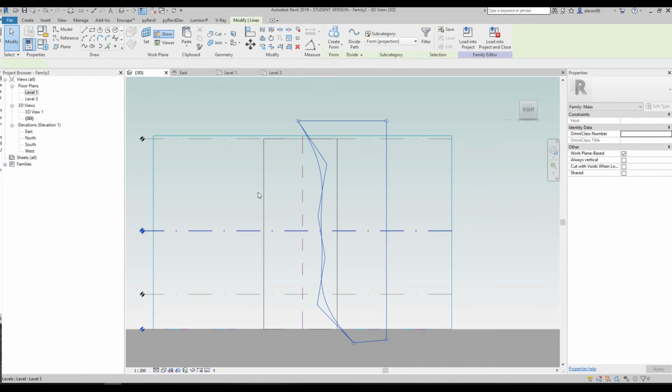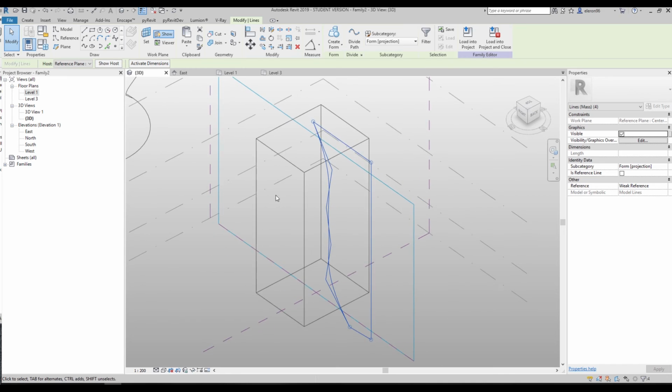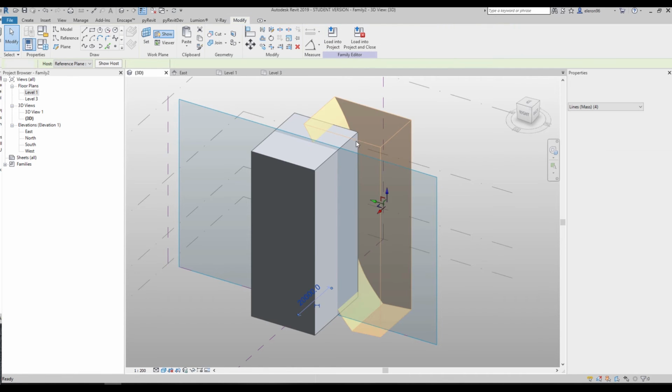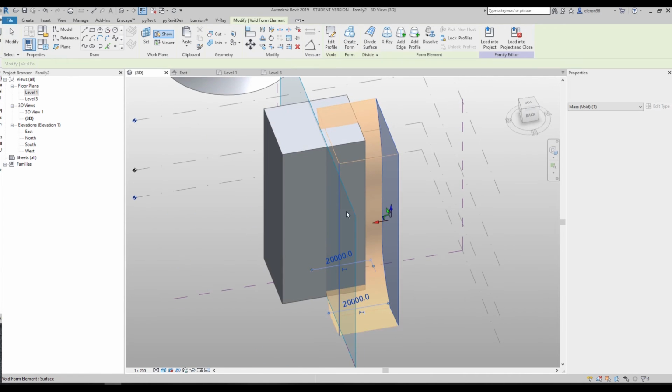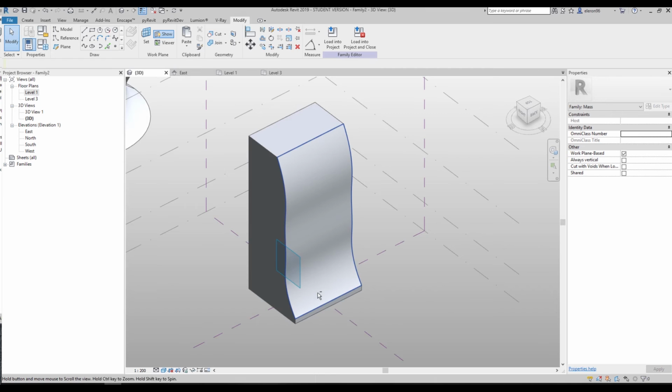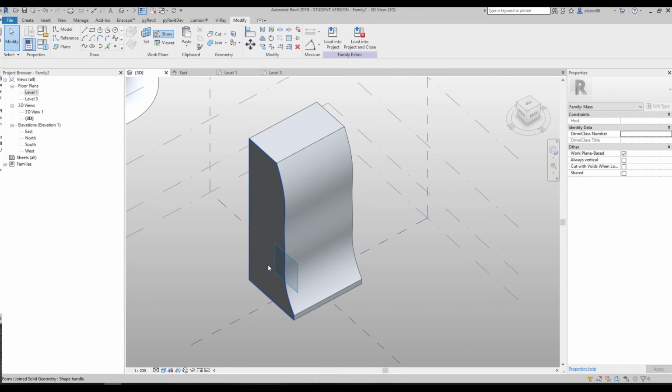Let's select all this shape, I mean all this profile. Let's change the view. I want to change the view graphic because I want to show you everything, and I will use the void form again. Create the void form from this spline. Okay, here is okay, but that side I wanna extrude too. On switch off, you will get this form, but it's only 2 directions.